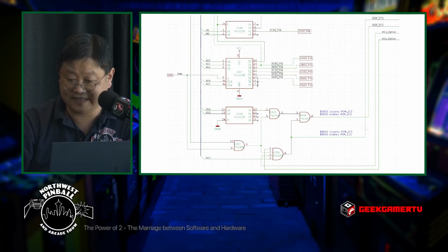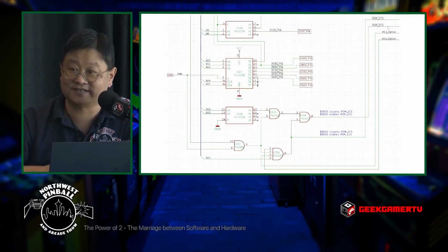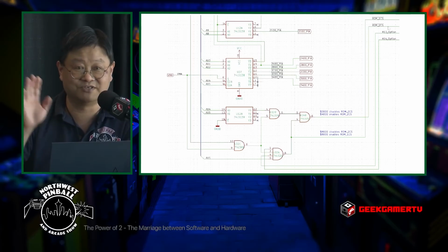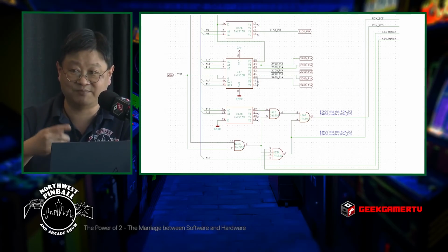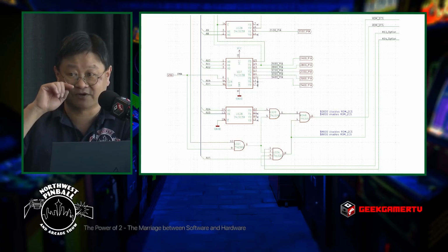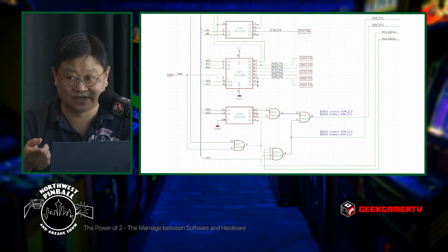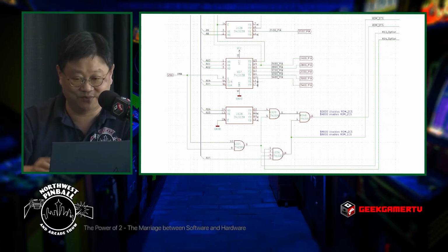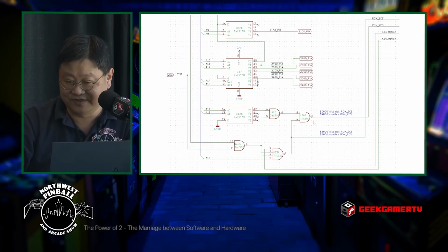That signal goes up to ROM2CS. Well, what that means is that as soon as this is 0, 0, ROM2CS is disabled because you've outputted a 1. The way to get ROM2CS to enable is to output a low. So what conditions output a low? In order for this to be outputting low, 0, it has to be fed 1.